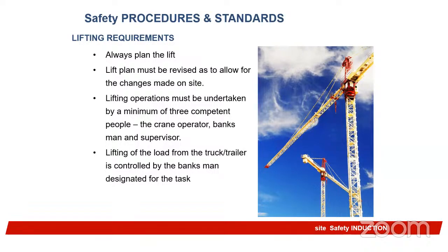So the lift plan must be revised to allow for the changes made on site. If you have new equipment, maybe you wanted to use the 40-ton equipment to lift a transformer of 1 ton, and later they brought the 20-ton, you need to have a review. Same thing, you wanted to use basket lifting before, but now you say let us use straight line lifting. You wanted to use the sling before, but now you say let us use a belt or whatever. There are changes. Then changes that are made will give rise to a review of your lifting plan.